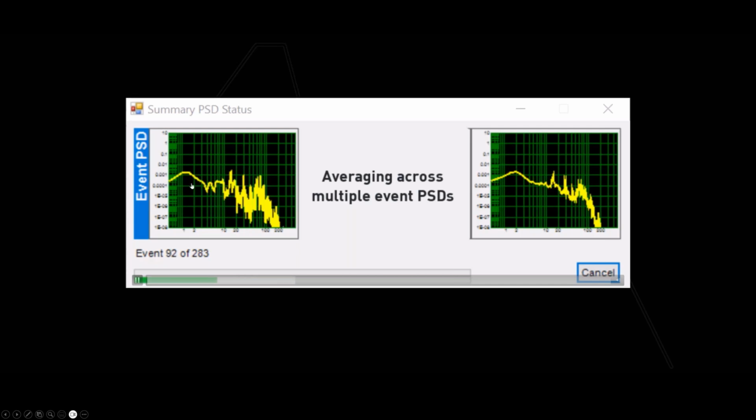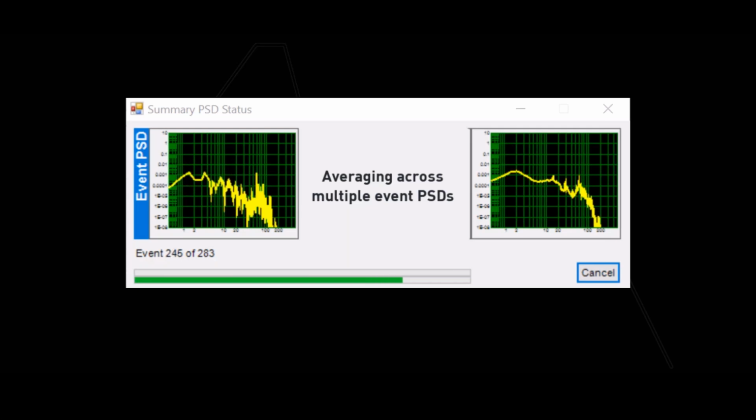So you see here all the individual PSDs that were recorded, and this is a summation of those that's being calculated as we average those together. That's just the simplest way of looking at this data when we do transport measurement: instead of just creating a PSD for one event, we typically gather thousands of events from transport and average across them, or do math across those.